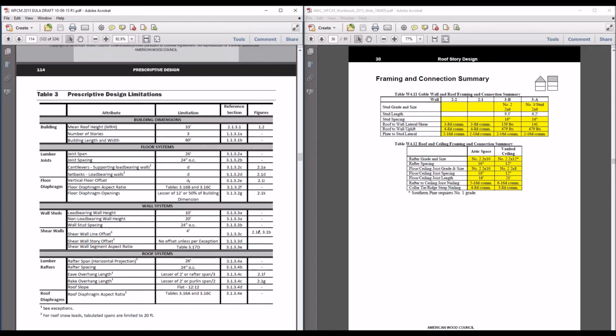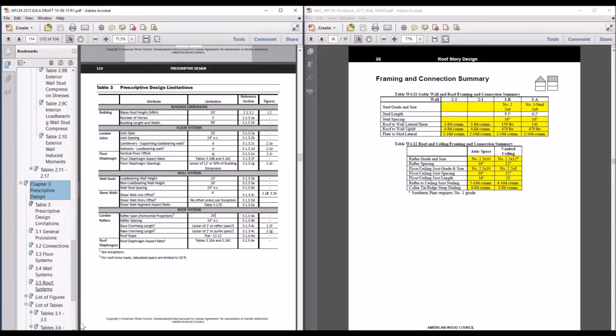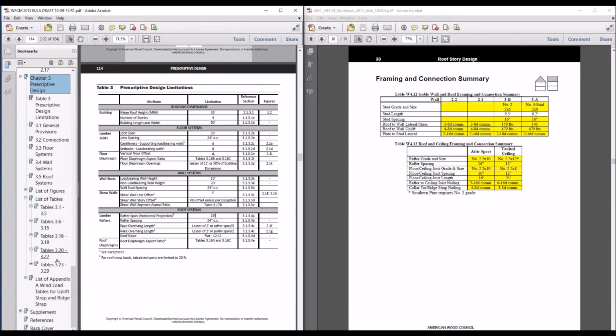All right, and I think we've got time for one more. So we looked at the span tables in 3.26 earlier. We had a question come in about which load combinations we used from ASCE 7 when we calculated those. Great, great. I forgot to come back and talk about that. Actually, we'll spend a little more time on it next week. Since we only took a look at the gable end walls today, we didn't really talk about what we do with load-bearing walls. So let me just touch on that briefly.